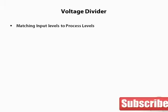Let's solve a real-world problem, matching sensor input levels to A to D process levels. Let's assume we have a hardware platform that accepts 0 to 5 volt signals. But the only sensor we could find to measure our physical quantity produces a 0 to 10 volt signal. We need a means of scaling the signal from 0 to 10 volts to 0 to 5 volts in order to be able to use the sensor.